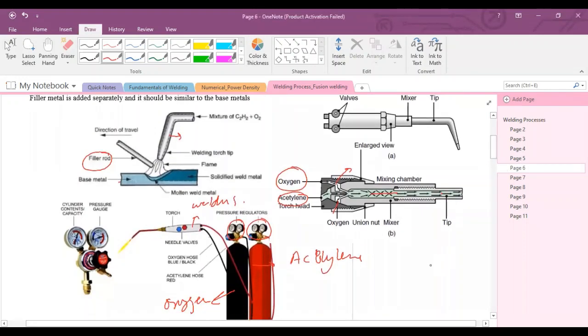During welding, acetylene is the most popular fuel in oxy-fuel welding, because it is capable of a higher temperature than any of the other gases. The temperature will go around 3500 degrees centigrade, or 3480 degrees centigrade. And it is a two-stage process. The two stages are visible in the oxyacetylene flame, as I have